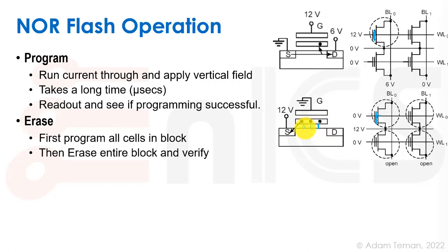And so it's going to actually be self-limited. The more charge that jumps onto the floating gate, that's going to limit the field over here, and then less charge will be pulled. So first of all, we can go and we can program the whole thing. So we bring all the cells to be pretty much a similar VT. And then we go and erase the entire block. And the entire block is the thing that is hard to know if we erased it enough or whatever.